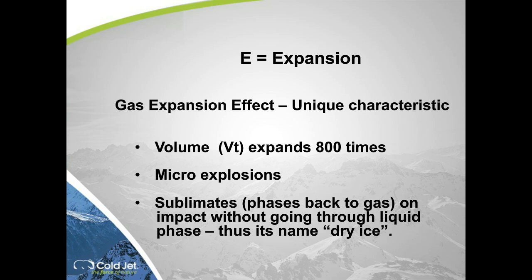So all these little micro explosions go on the surface, and they just blow the contaminant off of whatever substrate you're cleaning. So it goes back into a gas, and it's dry, and thus the name dry ice. And that's the magic of it. The kinetic energy is common to some other blasting media, but that thermal property and these expansion properties are very unique to the magic of dry ice.